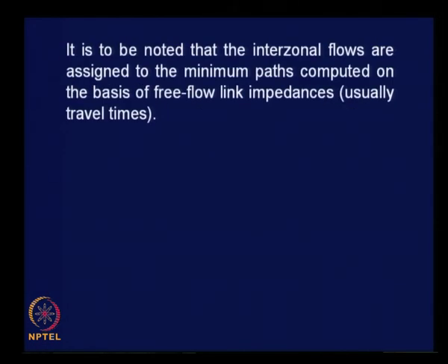And it is to be noted that the interzonal flows are assigned to the minimum paths computed on the basis of free flow link impedances, usually travel times. So, whatever travel times we have been talking about so far are free flow travel times.